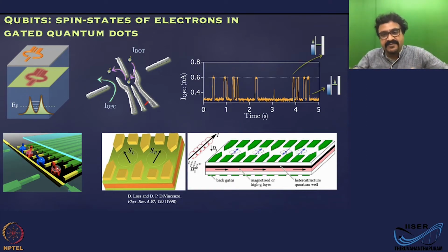That means if you have a wafer which is large enough, and you have lithographic facilities provided by microfabrication technology, you can make n number of these quantum dots, and each of them can host bits of quantum information. And you can do spin states. You can apply a field, and you can use the Zeeman split states of the spin states in the field to store information.